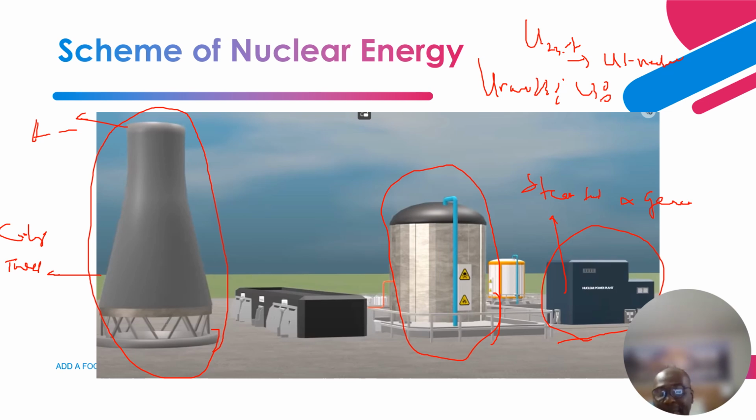The steam turbine itself has a shaft that has turbine blades, and those turbine blades have been sectioned into a high pressure section, intermediate pressure section, and low pressure section. There's a coupling here, and this is the generator shaft. So the generator is here, and the steam turbine is here.